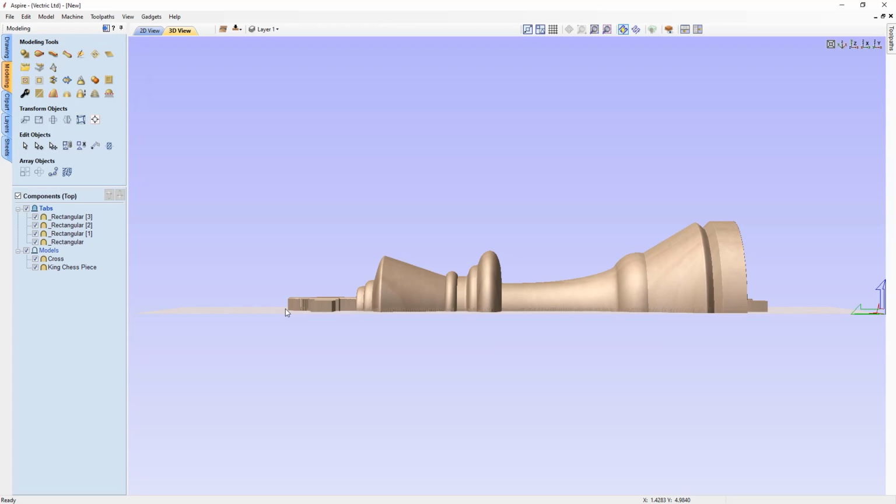And that'll make more sense in just one second. So let's go over here to our component tree. Let's right click on that, and we're going to insert a new level. Right click on that and we're going to rename that. And we're going to call this limit plane. And we're going to turn this into a combined mode.